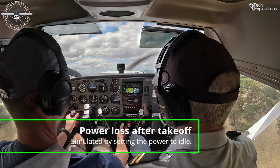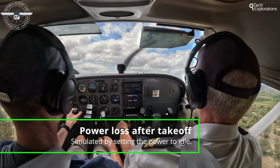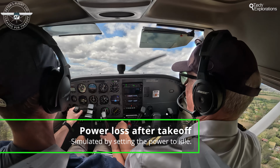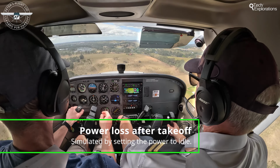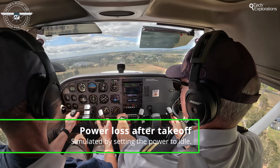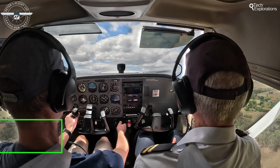In hour 15, right after takeoff for circuit 3, we did a quick demo for power loss after takeoff. Of course, we didn't land in a paddock, but we set the power to idle for a few seconds and spotted a suitable patch of land to land within 30 degrees arc to the right of the flight path. You can see this at the 31st minute and 18th second in the hour 15 video.